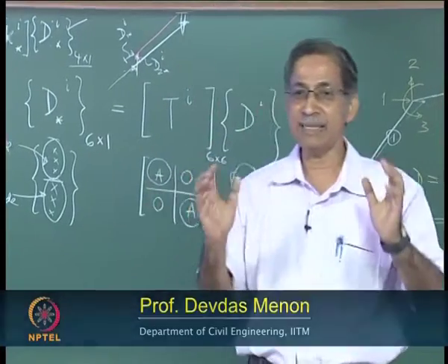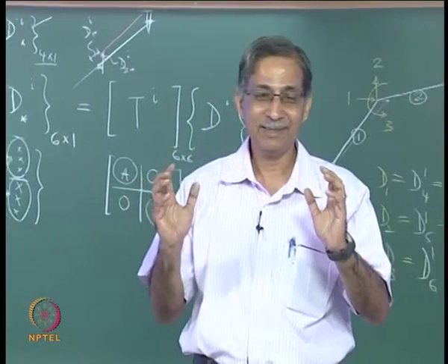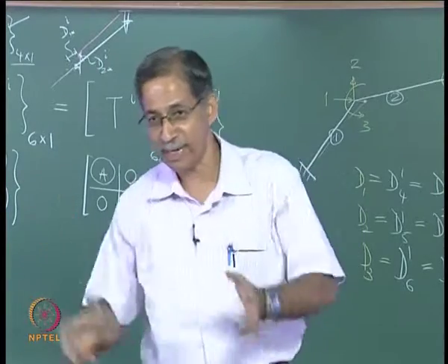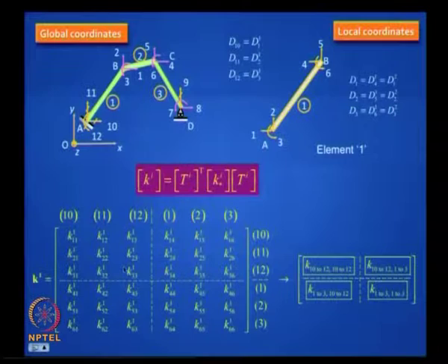So you got an element stiffness matrix contribution. It is like a donation coming from the state party to the central party. So it should go to the right slot. Are you clear? So this will go to 10, K10 to 12, K10 to 12. This part is 1, 2, 3, 1, 2, 3. So this will go to the upper left corner. Please listen carefully.